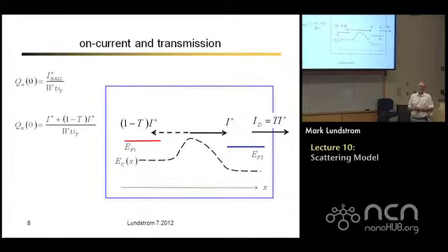I'm going to make an assumption here. It's not completely obvious. The positive flux comes in at the thermal velocity out of the source. When it backscatters, what's its velocity? I'm going to assume it's about the same, and detailed simulations show it's close. So I'm assuming that the backscattered flux is traveling at the same velocity. So if I want the total charge, I just divide the positive flux and the negative flux by the velocity and add both together. I'm not subtracting them. For the net current, I would subtract them. But I'm adding the two because they both give me carriers. And that's my total carrier.